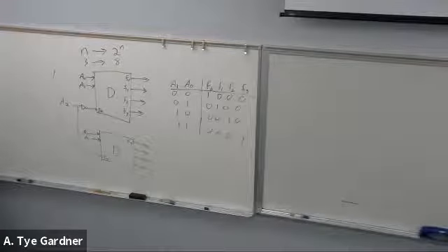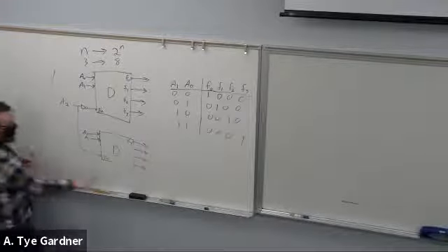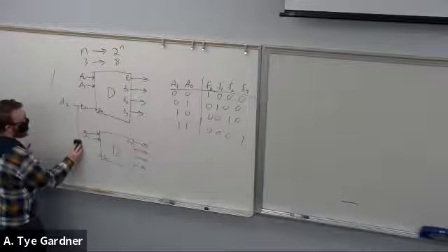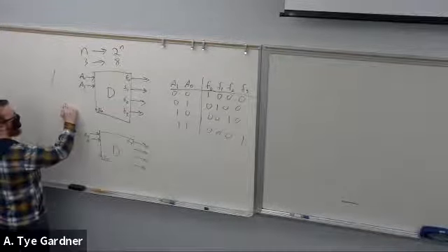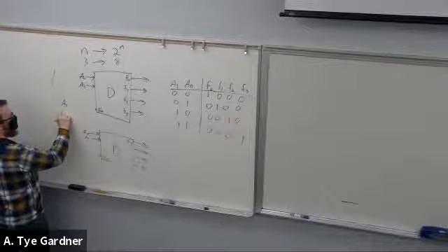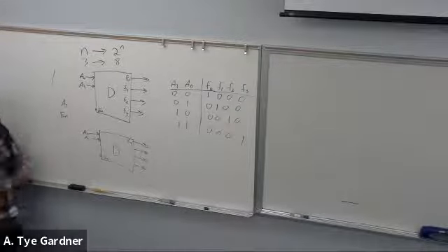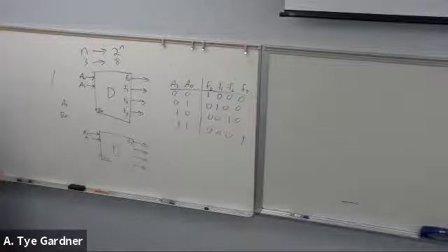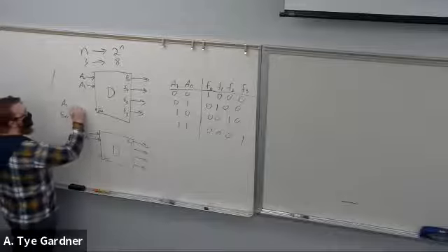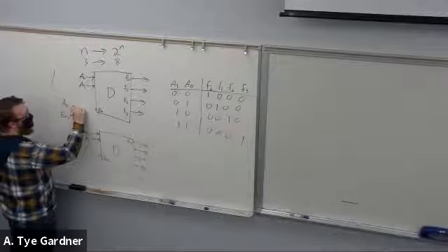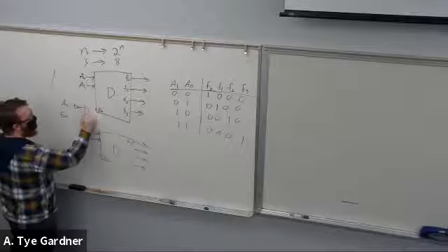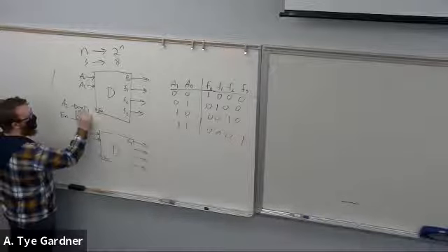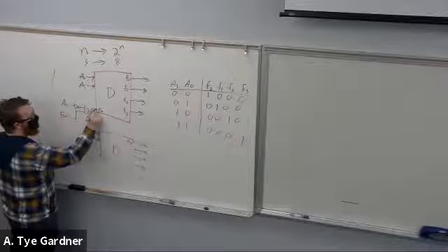Well, then all we have to do is use 2 AND gates. Same kind of thing, we're still going to have A2, but we're going to have an enable signal, so a 4th input. And then I'm still going to invert the A2, but I'm going to throw it into an AND gate with the enable.